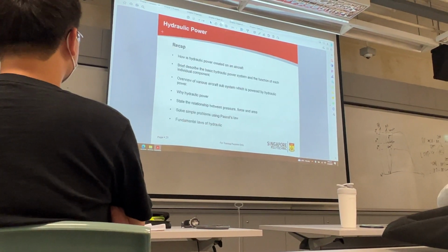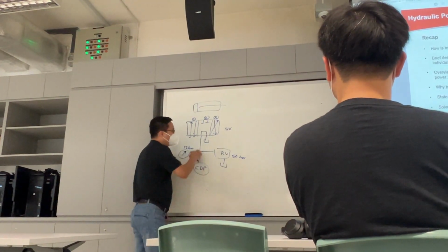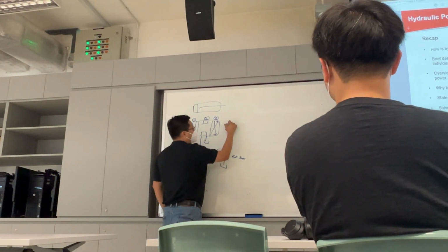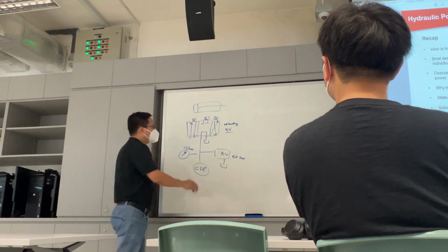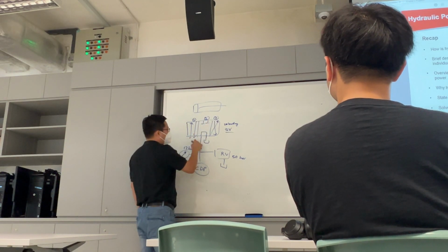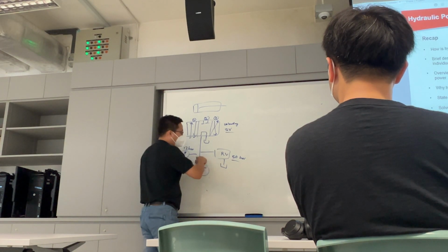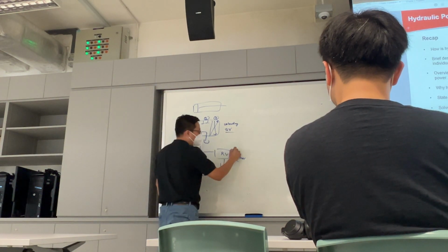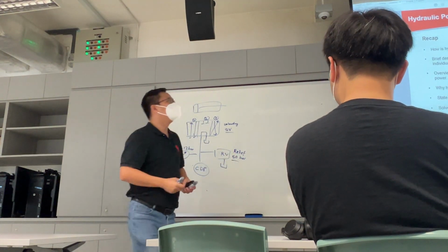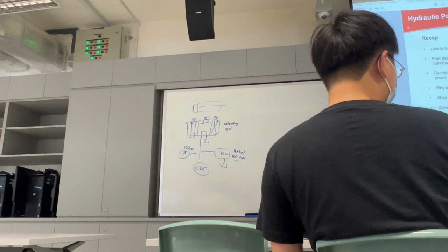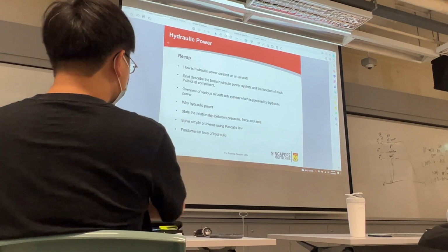Alright? Some words that you all must remember. When the fluid is going out from here, we call this unloading fluid from the selector valve. If I do extension, eventually the resistance reaches at full extension, what is the value? 50. So the fluid went out to the reservoir. In this case, we use the word relief. Be careful how the exam asks you. Only when the fluid goes out from the relief valve, we call it relief. All else we call it unload.